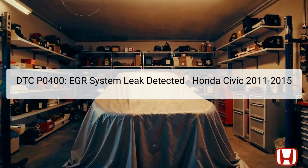It's vital to address any leaks in this system, as they can lead to increased emissions and potentially affect engine performance. The EGR pipe, EGR valve, and related components are primarily affected, and proper functioning is essential for the vehicle to meet emission standards. In this troubleshooting process, it's important to record freeze data and any onboard snapshot before proceeding to ensure a thorough diagnostic approach.